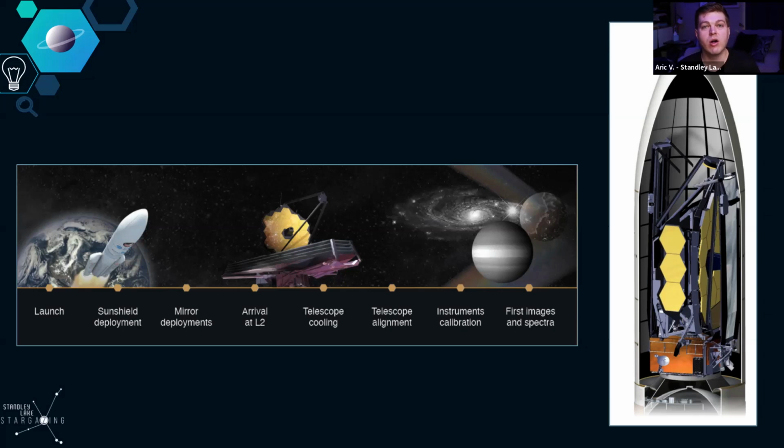You want to have alternate routes for information to get through. And this applies to everything. This isn't just one aspect. This can be mechanically, this can be with the guidance and navigation, this can be with the optical side. All of the instruments on board, both the detectors and then the spacecraft operations, so like the star trackers, the alignment equipment, all of that has to be able to work with some failures, because nothing is ever perfect.